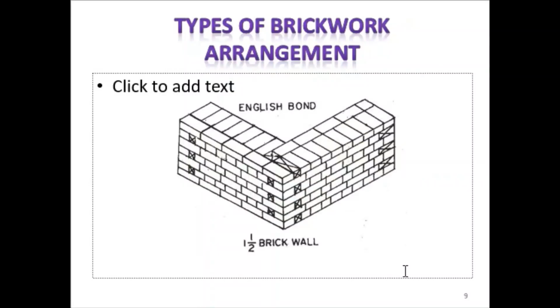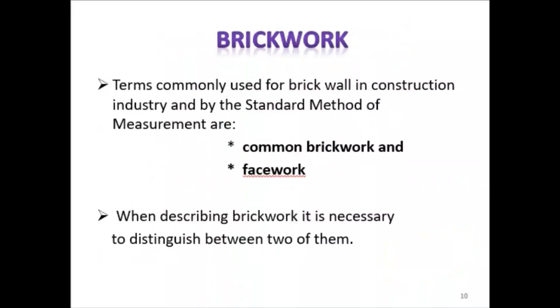So it depends how your architect or engineer specifies the construction of the brick, and the contractor will follow, and they will have a different pricing for the way the brick is arranged and the number of material being used. If it is a 1.5 brick wall, of course you will use more brick so the thickness will be increased. So normally this is suitable probably for a gate, or for a type of wall that requires more soundproofing or better thermal insulation.